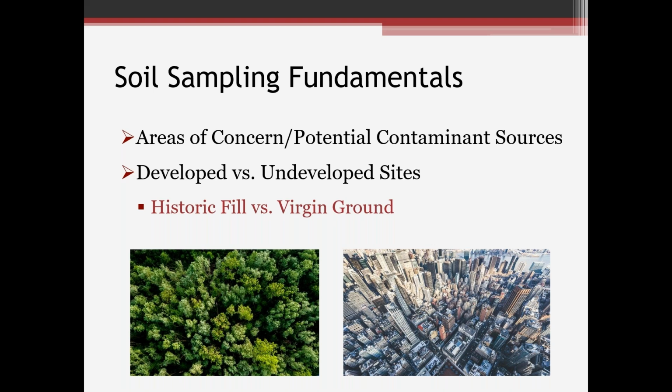If you're dealing mainly with soil that you're just trying to maybe reuse for backfill, okay, how much of that soil is going to be excavated? What depths might you be excavating? All that will come into play in limiting the area of investigation to make sure we get the best available data for the purpose of that sampling event.